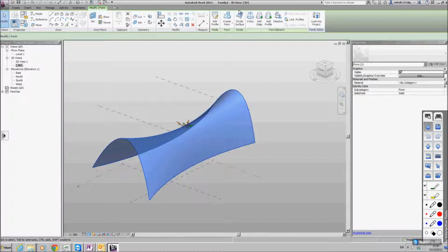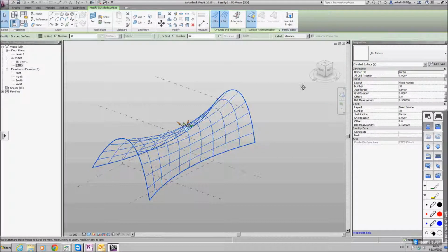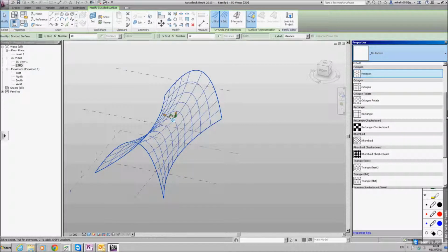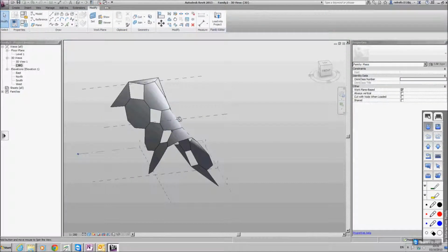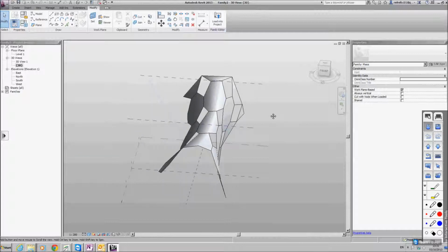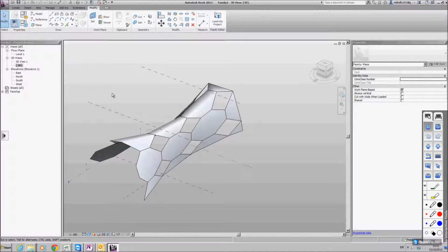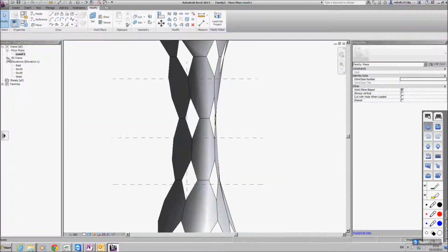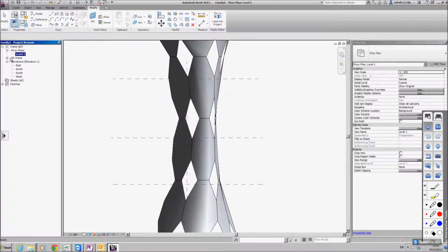I'm just going to click on this shape, and I'm going to click on this subdivide. Divided it, and I can apply a pattern to this. So there's a few predefined patterns that we can work with, and that is a pattern that we can place onto it and use as grids. So that's just a quick look at this conceptual massing environment. So it is a bit different to what we're used to. That's where you would make some possible massing.